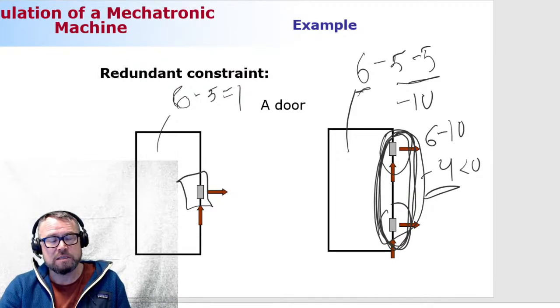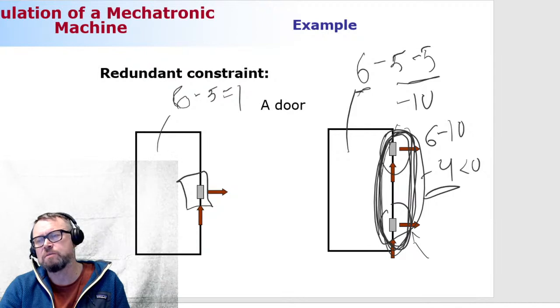That is called a redundant constraint. Most commercial software can automatically identify a redundant constraint and eliminate it, or they may not. So it is not a good modeling policy to use redundant constraints. Try to avoid them as much as you can.